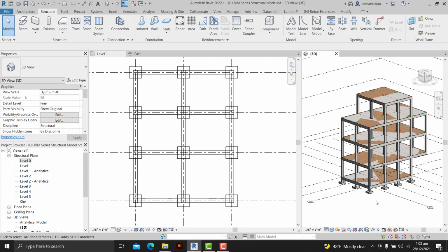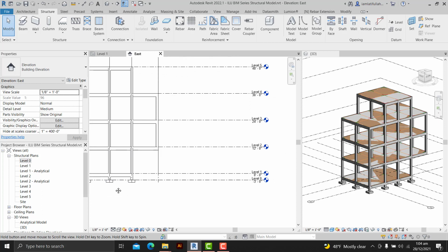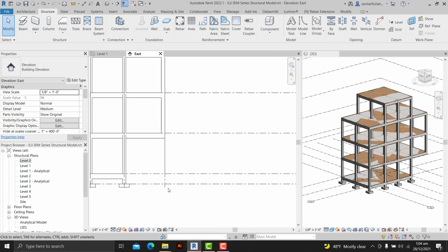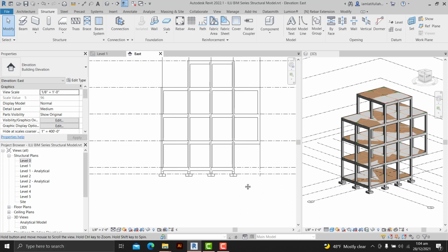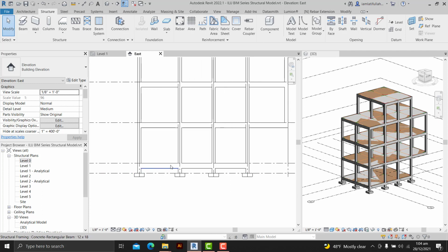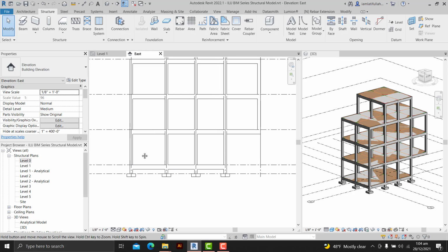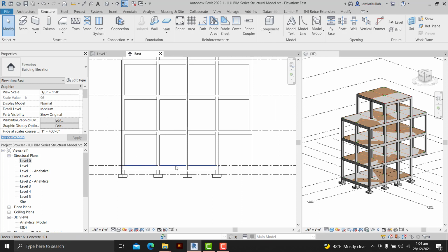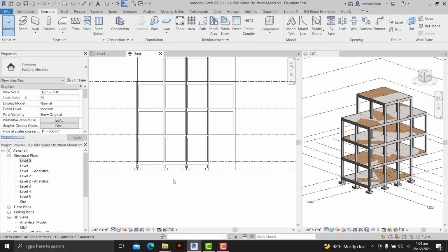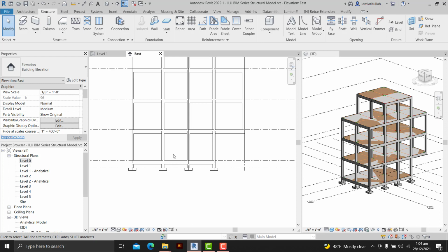So we would be following that, but before that I did some changes in the model. If you see, I have added this new level, which is level 0, 3 feet from the ground. This is just to give a space for excavation, so a 3 feet excavation would be executed, and then these foundations would be laid out, then the columns, the beams, and then it would be covered and filled with earthwork again, and then our floor would be laid, and after that our structure is going to proceed till the last story. So one element is still missing, that is the stair.